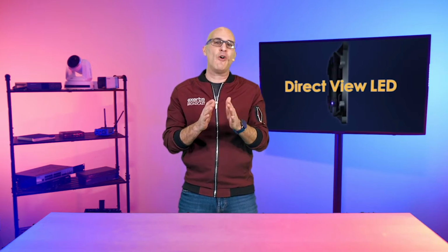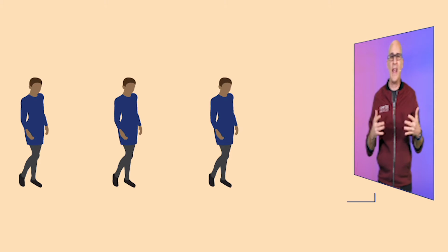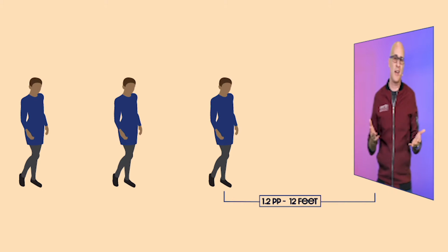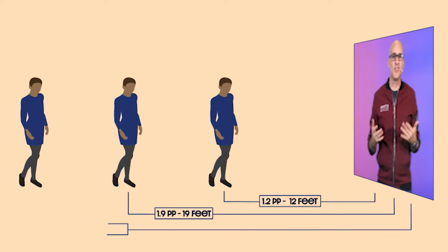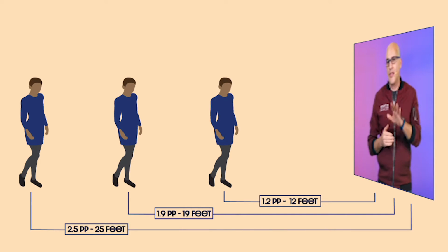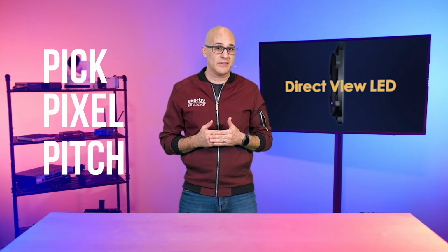What matters most is how far your audience is from the screen. As you get closer to the wall, there's a point at which your eyes can see the space between the pixels. Each millimeter of distance between pixels equates to 8 to 12 feet of optimal audience viewing. So a 2.5 millimeter wall has an optimal viewing distance of roughly 25 feet. Now this is where you can save the most money on your wall. Pick the pixel pitch that matches your audience before you pick the size.